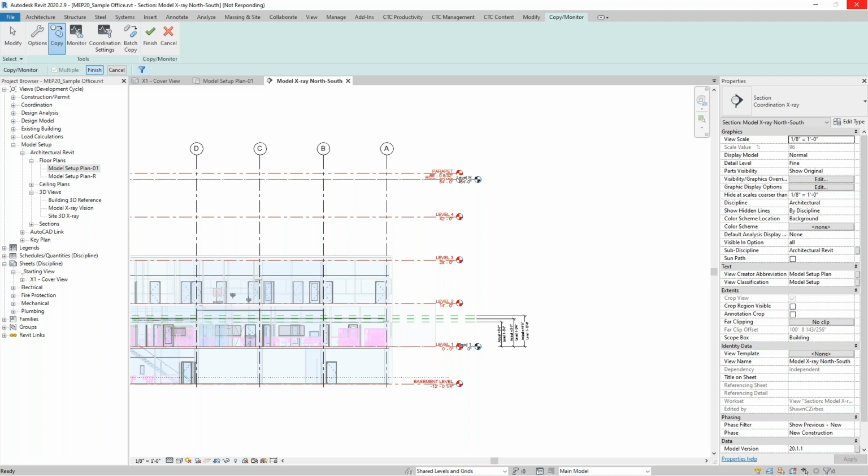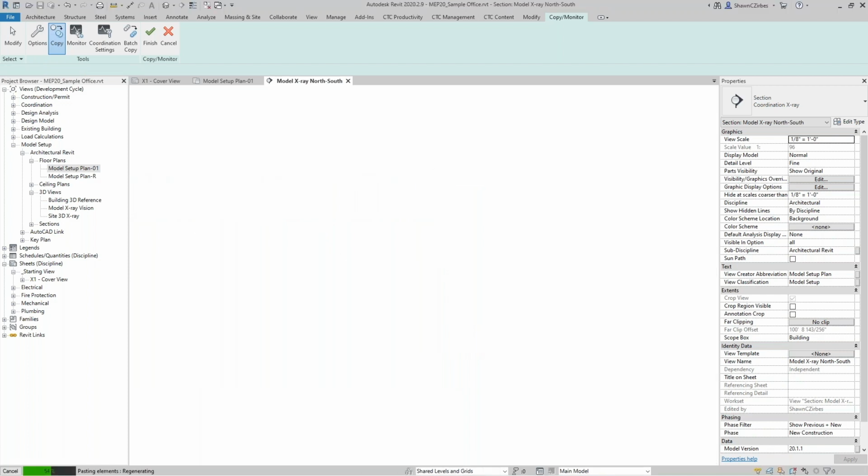When you cut your template, if you're making a brand new template for yourself, when you cut that from the starter project model and you save it, one of the things you're probably going to want to do is make sure that the work set you leave it on, just like how I left my project browser neat, or should have, is the one that you want users leveraging right away when they first start. Because when people first jump into a model that has work sets and they start doing all this setup, they tend to forget to set this.